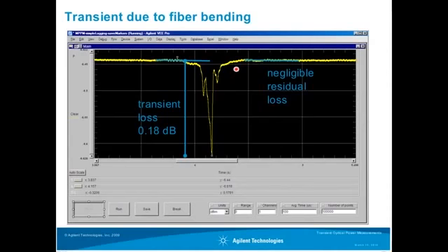The two things that people look for are how big is the transient, and then whether there's any residual loss afterwards. Has the device or system been permanently changed due to this? This measurement, just to get used to looking at this again, is shown on a dBm scale. We've chosen a certain power range for the measurements. 0 dBm was enough to capture these signals. They're about -6 dBm, sampling at 100 microseconds and taking 100,000 points.